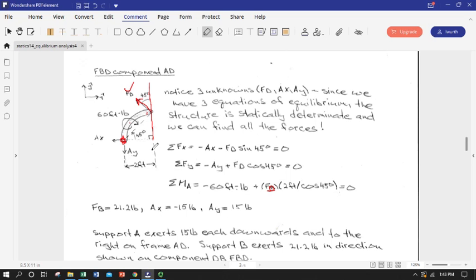So if we use the right hand rule, this 60 foot-pounds is actually pointing in the negative k hat direction, and we can use a little bit of geometry, the r cross F, so we have a radius from A to the point of application of point D, and this is actually forming quite handily a right angle. So all we need to know is the length of this.